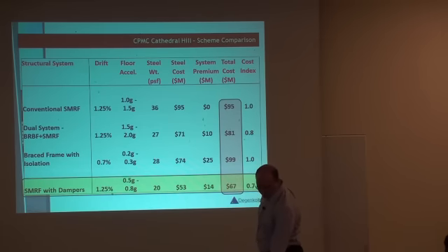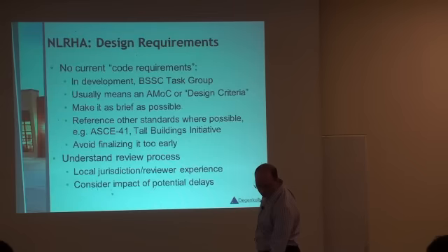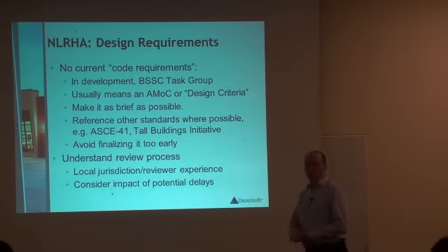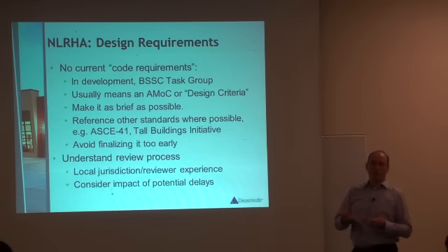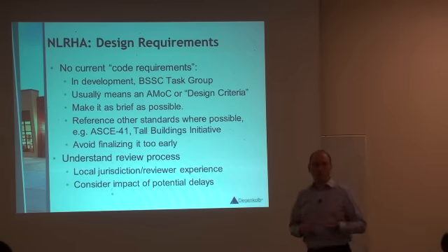So this shows you that in many cases you can save a lot of money. You just need to be careful not to overstate it. One of the issues with the nonlinear response history analysis is that at the moment the code doesn't tell you how to do it. You basically use your experience and you have to get it approved by a peer review panel. But each peer review panel can do its own thing.